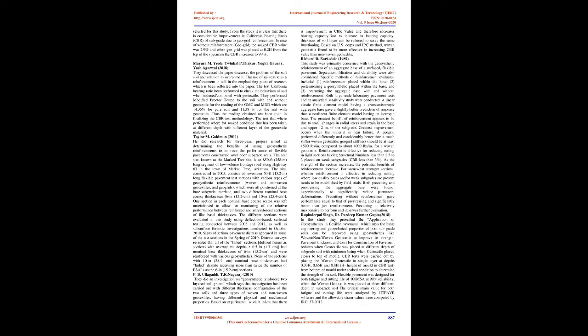They performed a modified Proctor test on the soil with and without geotextile to obtain the OMC and MDD, which are 14.35% for pure soil and 11.38% for the soil with geotextile. Thus the readings obtained were used in finalizing the CBR test methodology. The tests were performed in soaked condition at different depths with different layers of the geotextile material. Taylor M. Goldman, 2011. He did research for a 3-year project aimed at determining the benefits of using geosynthetic reinforcements to improve the performance of flexible pavements constructed over poor subgrade soils.